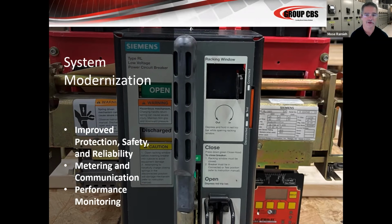Essentially, when the breaker is brand new, we put this trip unit on it and we test this breaker on the high current test set. We know that if the trip unit sends a signal to trip, the breaker is going to take, let's just say, 33 milliseconds to respond and open. So we can program this trip unit to say, hey, this breaker should trip in 33 milliseconds. If the next time this breaker trips it takes 50 milliseconds, it's still pretty fast, but it's not as fast as we programmed the trip unit.